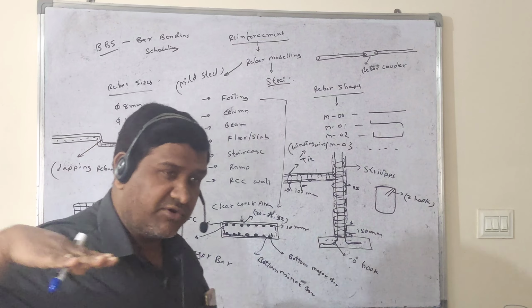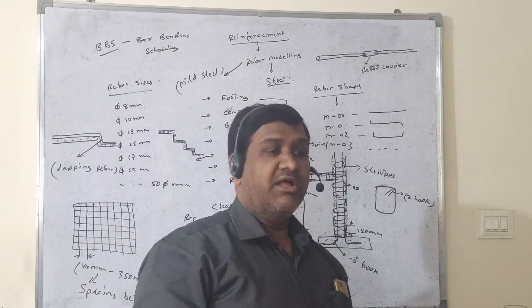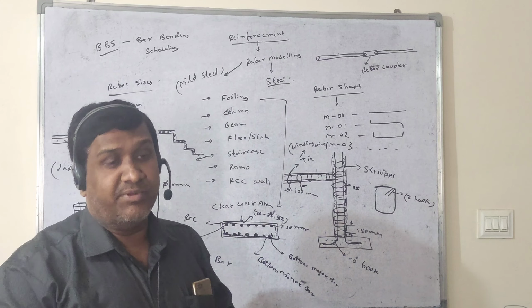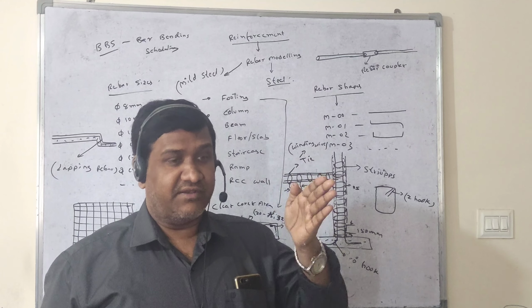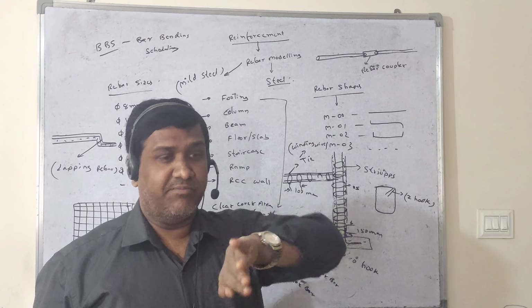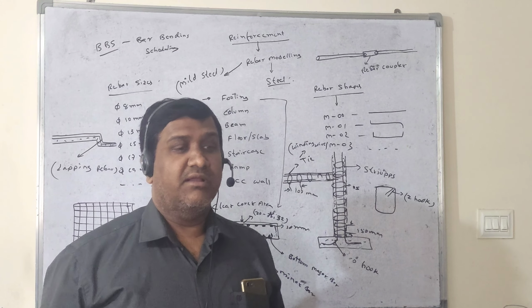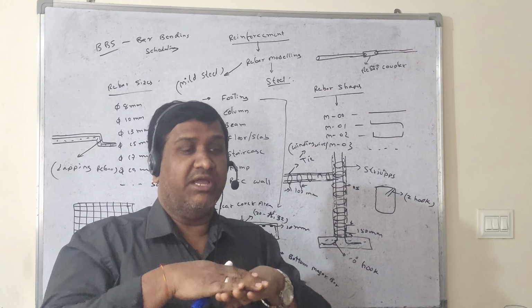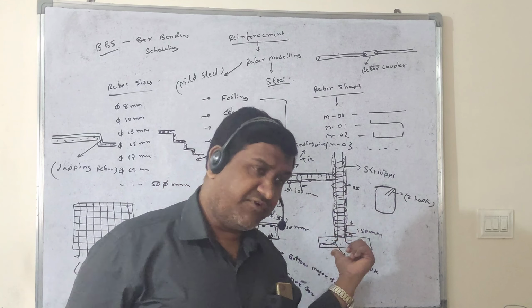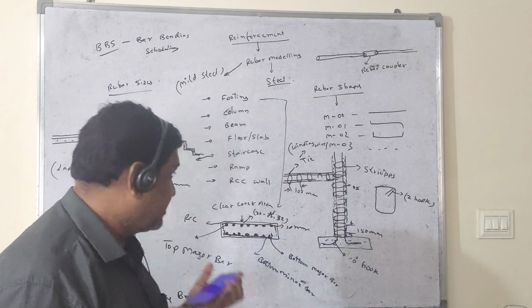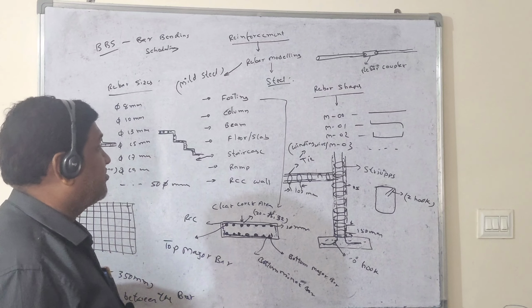One rebar will go straight, then the rebar will bend. It will look like a floor, because the tread and riser become bends like that, and they keep the rebar shapes one above the other. So in the staircase we can use this reinforcement.